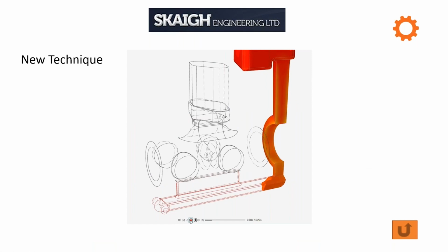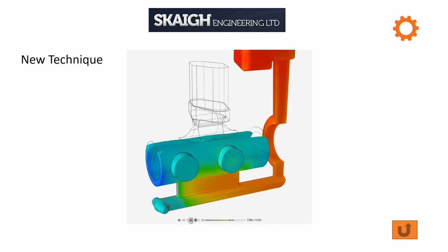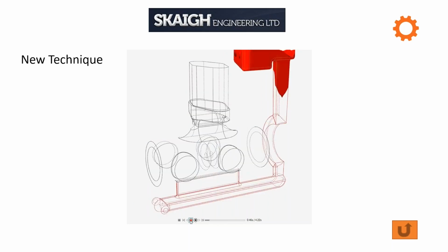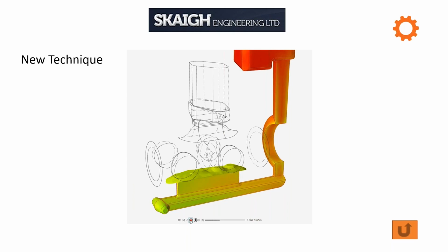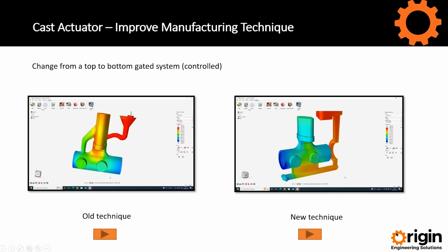So we've got a proper pouring base and a good target area for the pourer to pour into the well. So actually the gating system is controlling the fluid flow. We're not relying on the pourer. Obviously we've got to rely on the pourer, because he's got to pour at a steady state into that pouring basin and make sure he gets the right level of metal. But as you see, the metal goes down. We've got it very controlled. Nice wide ingate there to get a nice laminar flow. So yeah, we can see we've got a good flow happening, gravitating back into the feeder. So yeah, we've got a good technique.